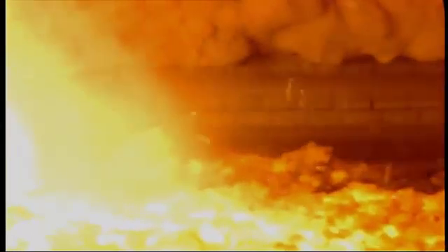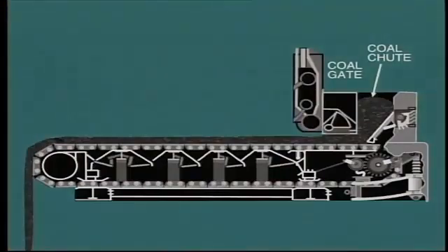Several inherent problems exist with this type of burning equipment. One is the potential for combustion to be incomplete and consequent discharge of combustible material into the ash pit and then to waste. Another potential problem is the failure of the coal bed to ignite, so that the whole bed of green coal may be discharged into the ash pit while the boiler rapidly loses pressure.